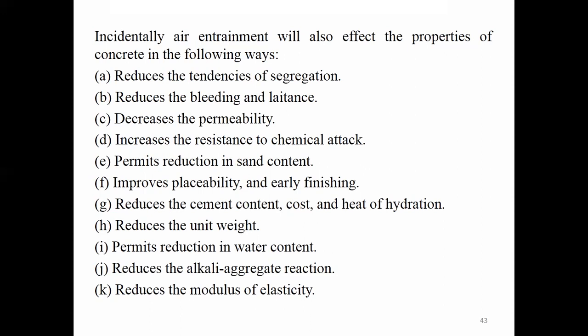There is a progressive decrease in the abrasion resistance when you increase the air content. For example, when you increase the air content to about 10%, abrasion resistance will be lesser when compared to the conventional concrete.